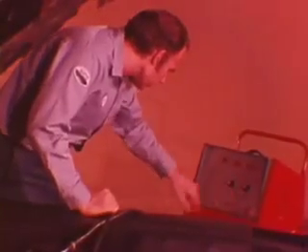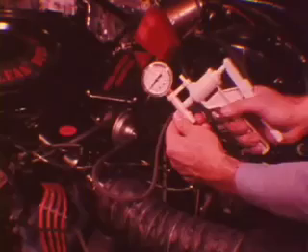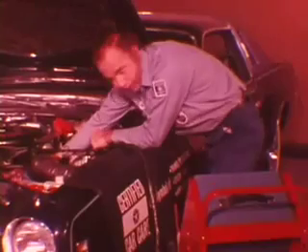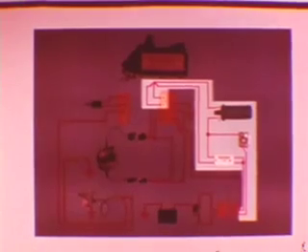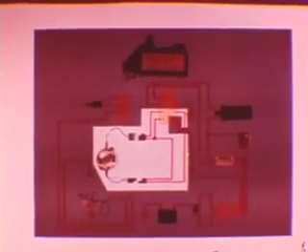Lean Burn System Analyzer offers the service technician a fast, easy-to-use, accurate, and foolproof method for testing the entire Spark Advance system, the complete spark control computer circuitry, the coil and primary circuit, the distributor pickups and circuits, coolant and carb switches, the throttle transducer, and the vacuum transducer.